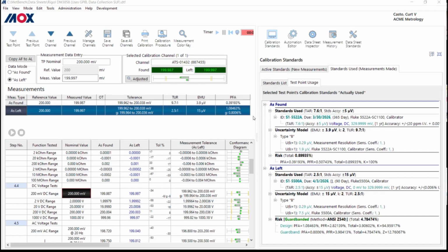So in MPS, you have global text files where you can set up storing those references, like coefficients or whatever, for instruments. Then at the time of calibration, you can have MPS, with the automation scripting, access those, and there are automation scripting commands to completely manipulate the uncertainty budget at the time of calibration. So you can have it clear the budget items, and you can have it calculate and add new budget items while the calibration is underway.